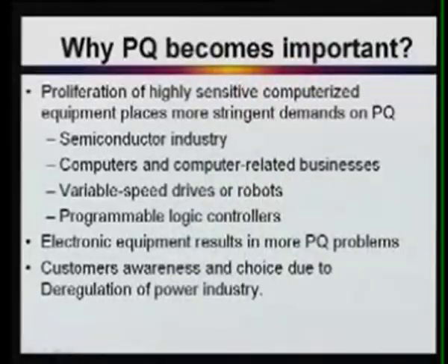Harmonics, as I said, are another PQ problem. Harmonics may be of different orders, lower order or higher order, and they may cause transformer and neutral conductor heating, leading to reduced equipment lifespan, audio hum, power supply failures, overheating of motor loads, maloperation of relays, and insulation breakdown.